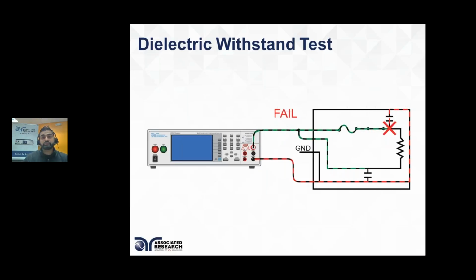And then we have a sensing circuit that detects arcing. So arcs are happening right before a breakdown happens between two metal products, and the arc usually happens through air or through some kind of material. And when an arc is happening, it creates high frequency noise on your current meter. So when we're detecting this high frequency noise, we're able to tell when a breakdown is happening due to the high frequency noise happening on the current circuit.